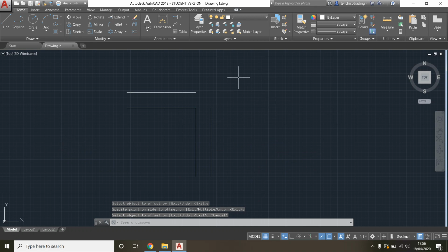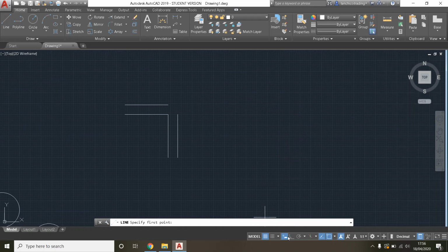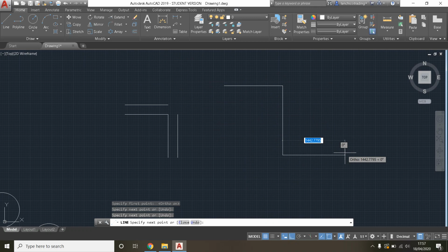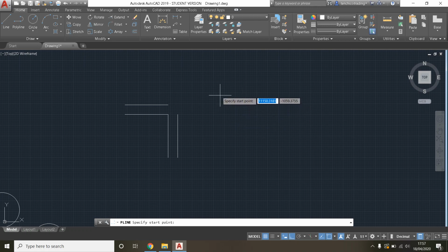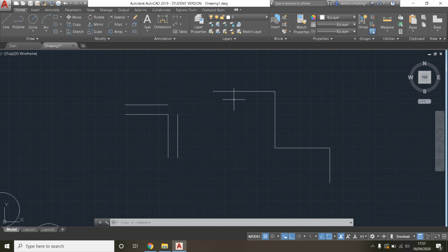So you can just draw a line. Let's quickly just draw it. Let me switch on auto mode, draw a line. Oh, you know what? Control Z, Control Z. Let's even make it fun and use polyline. Polyline. Remember, polyline is a line that does not have segments like this one. This was a normal line. Now with our polyline, we want to just offset it by 220.